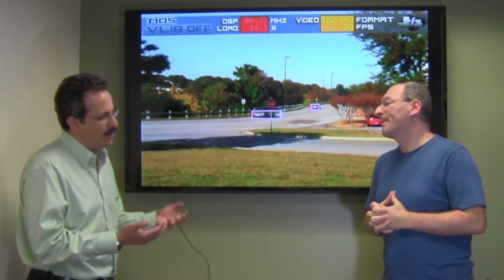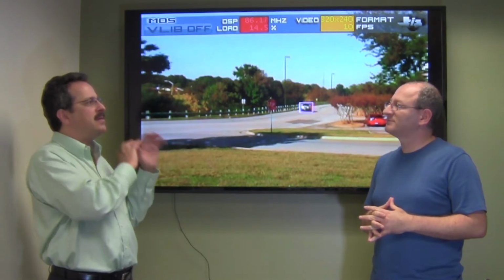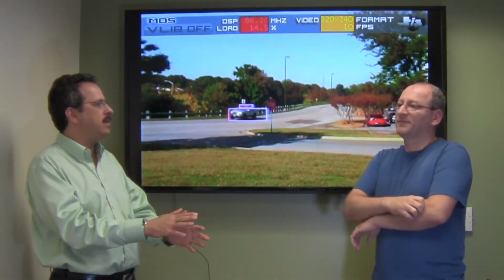So hopefully from the outset, as you're devising the algorithm, you have the kind of idea in mind of what sort of resources, data types, memory footprint, memory bandwidth, processor power is available to you, so that you're not designing an algorithm that's not going to fit in the target processor. And I assume then, or maybe you start without any constraint, but then once you have an approach that seems to work, maybe you look at, well, how can I simplify, still on the PC, the algorithm so it's more likely to fit in the resource envelope of the embedded processor.